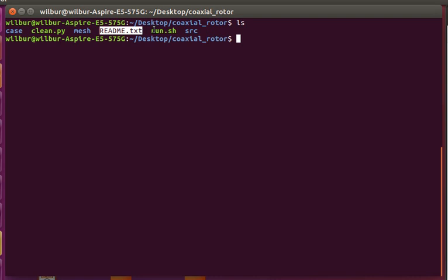In the default, if you put a negative sign on the RPM, it'll change your thrust direction. So it would be impossible to actually have counter-rotating propellers thrusting in the same direction. Well, I guess you could manipulate the lift coefficient data or whatever, but I'm not really sure. But anyways, even if you could, it'd be very inconvenient.